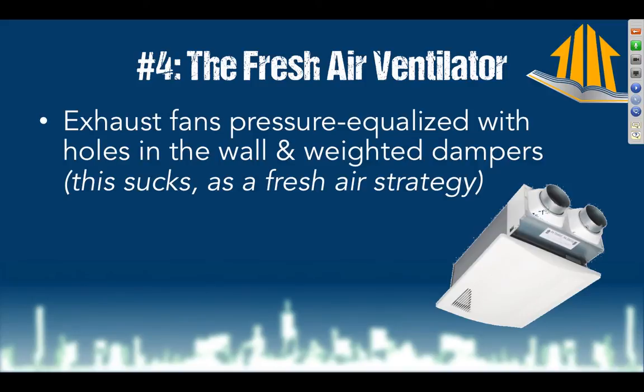Number 1, we need to remember that exhaust fans are going to need to be pressure equalized, because if I was really to run a 50 CFM exhaust fan in there, I'm going to depressurize the house like crazy. And if the door opens inward, and the door is not latched all the way closed, it's going to pull the door in, and it's going to open my front door every single time I turn on the exhaust fan. That's bad.